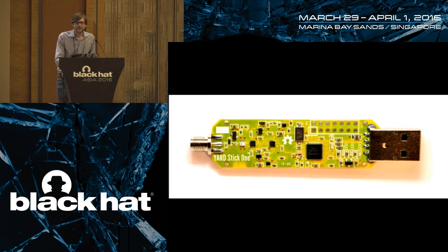And the key thing to know about the CC1111 or any of these wireless transceiver ICs that are on the market is that they provide a digital modem on a chip. So all the modulation and demodulation is done in hardware, not in software. With SDR, we do that stuff in software. With something like this, we do that in hardware. And so it's more limited. It's not so universal as software-defined radio. But it does a lot of the heavy lifting for us.